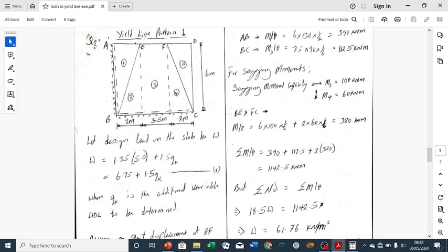And what is the reinforcement resisting the vertical component? Take note of this very well. The reinforcement resisting the vertical component is actually the horizontal reinforcement, M2, and the capacity is 100. That is why we have 100 here. For the vertical component of the yield line, this is the place of rotation, and this is the place of the yield line, and that distance is 2. That is why theta is 1 over 2. So this is the vertical component.